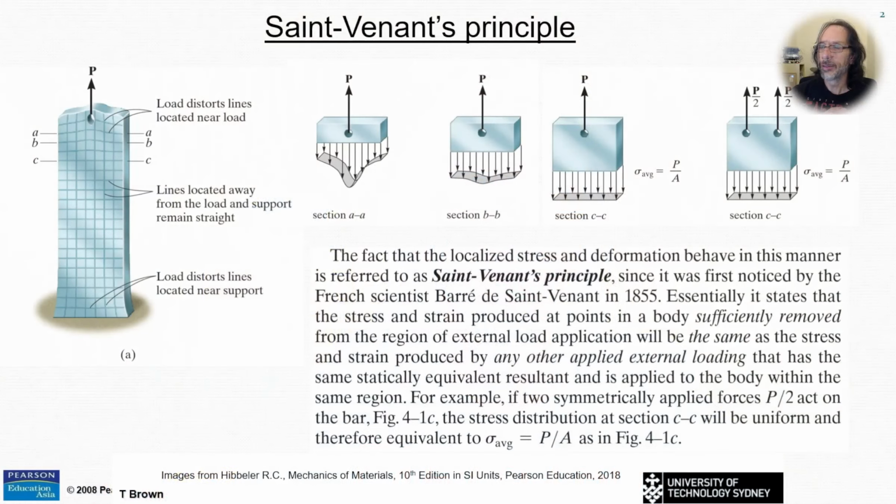This is just a screenshot taken from the textbook that we're using, Hibbeler Mechanics of Materials, the 10th edition. Basically, Saint-Venant's principle says that it doesn't matter how the load gets applied, the stresses and strains that are developed some distance away from where the load is applied are independent of how that load gets applied. So we're close to the load application region, here at section AA, for example.